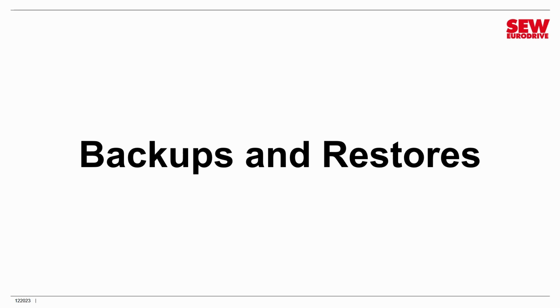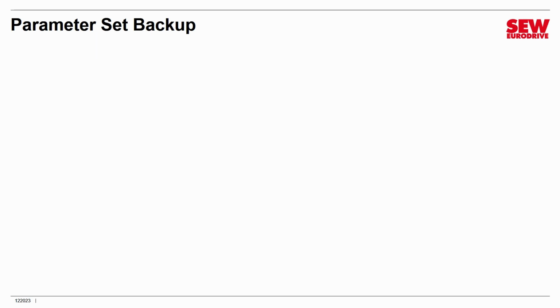Backups and restores can be extremely helpful and definitely can save you time. I recommend that whenever possible, you should always back up a VFD once you've gotten it set up and running, and then put that file in a safe place. You never know when that's going to save you some time down the road. It's just a smart thing to do. So let's talk about how to do backups and restores.